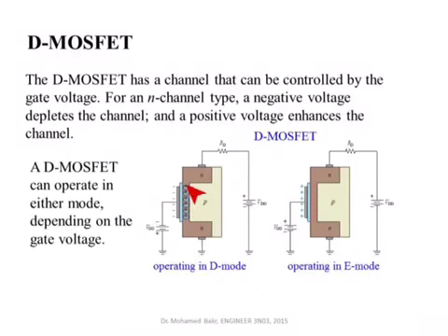In order to remove these electrons and cut off this region, you have to apply a negative voltage between the gate and the source. This negative voltage will make this capacitor negatively charged, so the electric field created through this capacitor will repel these electrons, will push them away from the conduction region, and then will leave only positive ions here, and this will stop the conduction of the current. So the D-MOSFET is a naturally on transistor. When VGS is 0, there will be a current flowing from the drain to the source.